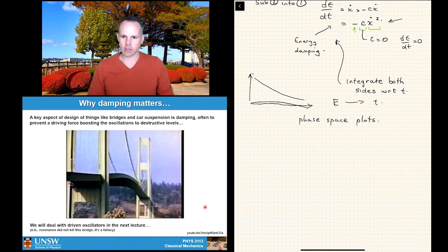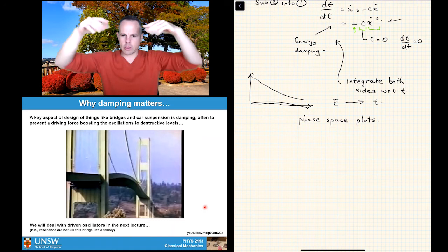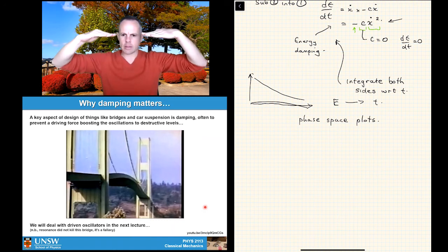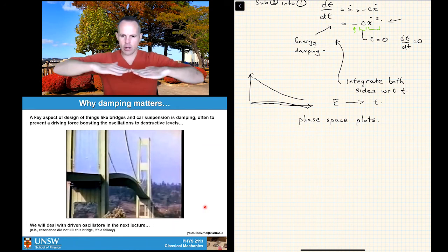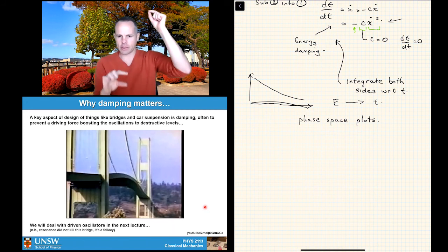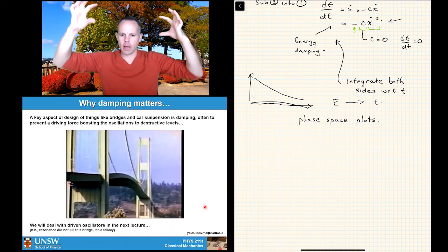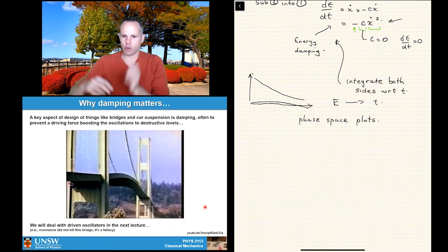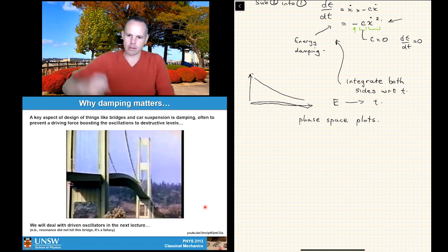So if I think back to when I was a PhD student, I had a very large fridge that took samples down to fractions of a degree above absolute zero, and it was suspended from a frame hanging from the ceiling. And when you get down to those sorts of temperatures, the vibrations that you get from just motion in the room through to the fridge on its mount swinging backwards and forwards and so forth sloshes the liquid helium around. That sloshing of the liquid helium around turns up as a temperature rise down in your sample, and so you end up having to, for example, build air cushion systems to try and knock out those vibrations, both to get the temperature down, and also if you're doing electrical measurements, for example, you've got a sample in a magnetic field. If that sample's moving in that magnetic field, you get currents, and you can detect those as well.